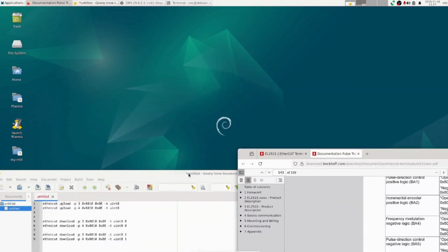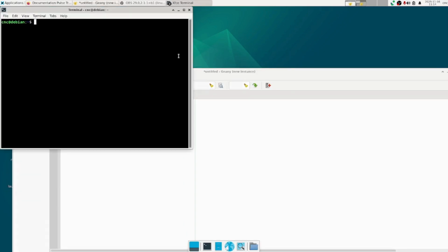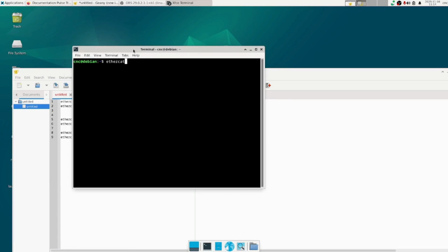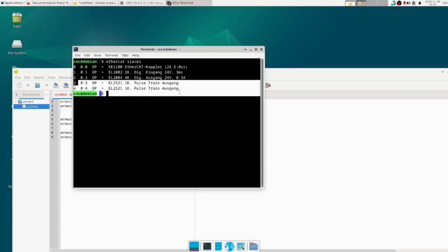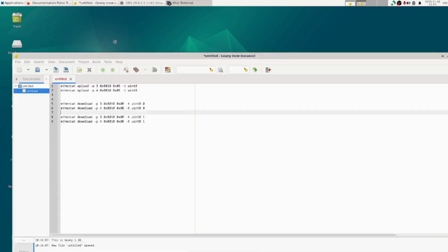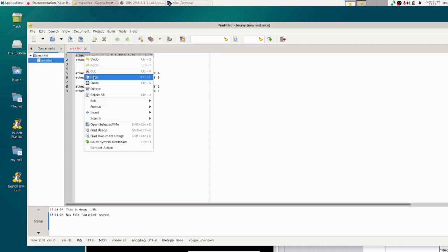I have prepared some commands. We are going to open the terminal and first of all type ethercat slaves. So we can see our EL2521s are slave number 3 and 4, and that's what we are going to use for the commands. The first command here is the upload.